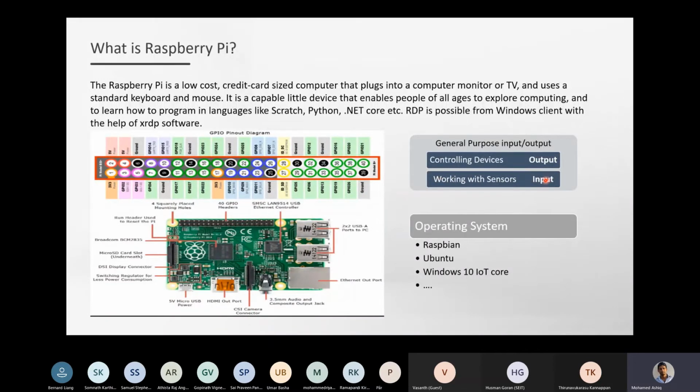So the two apps which I have done here, which I'll be demonstrating in this session, are going to be output, not input. Maybe in future sessions we will also collect data with the help of sensors. For example, if you have a temperature which needs to be measured and sent to the cloud, in that case you'll have to set the GPIO pin to input. It can be any pin here, whichever has GPIO, right?